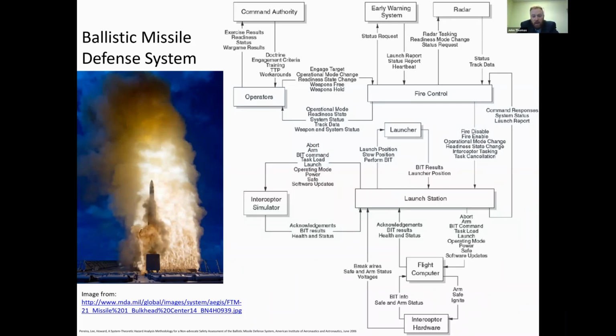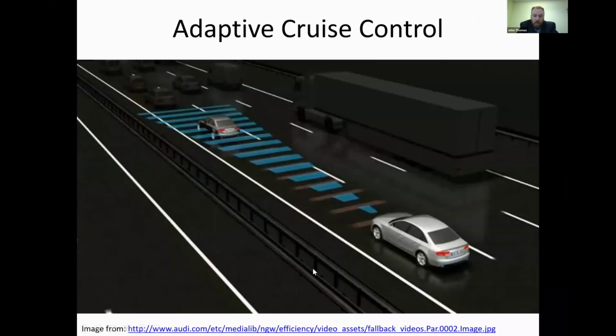We could send an arm command followed by a disarm command, but at the other end, what you receive could be a disarm command followed by an arm command, and that would leave you one step away from inadvertent launch. So STPA was used on this system to find a large number of scenarios just like that. That took a long time to address.